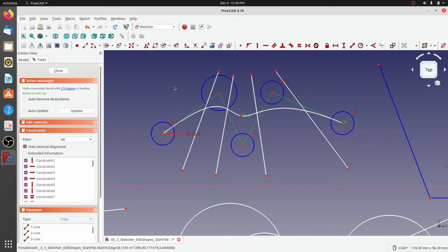So why am I telling you all of this? What I'm trying to say is that the trim tool in FreeCAD will only trim till the edge which you can select. Just to make my point, let's trim this inside segment of this line and see if it stops at this green line segment, which is connecting these 2 center points, or does it stop at the circle?